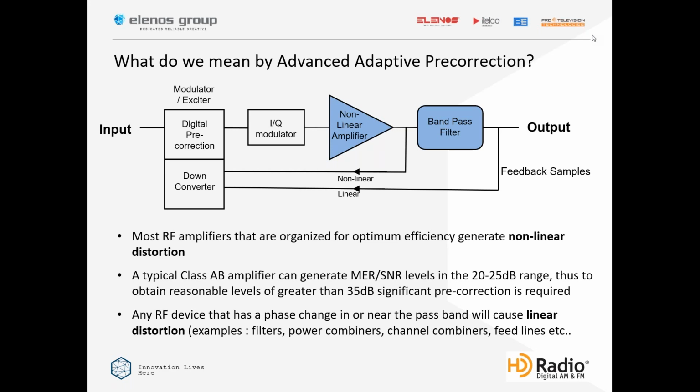The other thing that this slide points out, Perry, and I think we should mention, is that the other HD radio equipment on the marketplace, including the part that has been developed by Broadcast Electronics over many years, has only a nonlinear sample. That is the part that is coming from the output of the PA and coming back and being corrected.